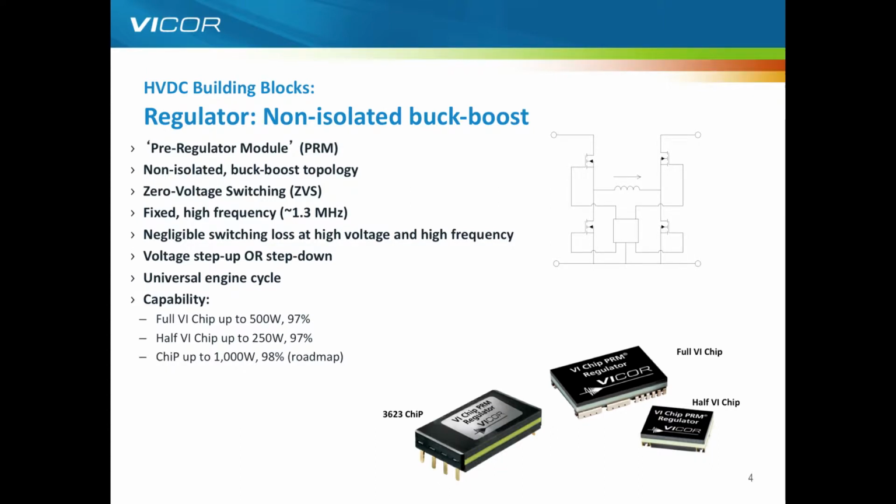It's zero voltage switching, and we'll go into the details of that when we look at the waveforms, which means that we can turn the devices on and off very quickly, which means we can improve the frequency of the device, which means we can have higher performance magnetics and a smaller size, less parasitics in the circuit board, and a continuing positive cycle of features which result in very small, very high efficiency, very power dense building blocks.